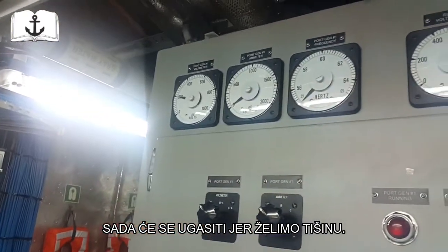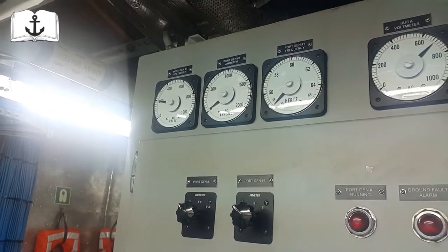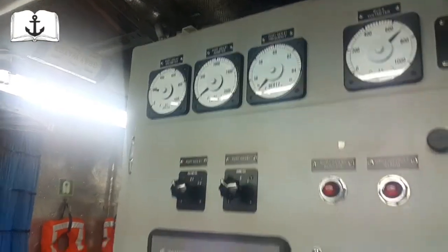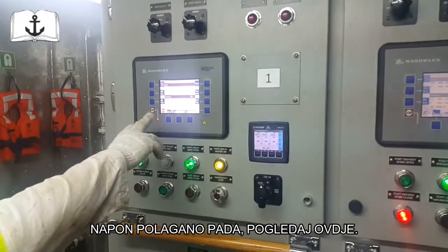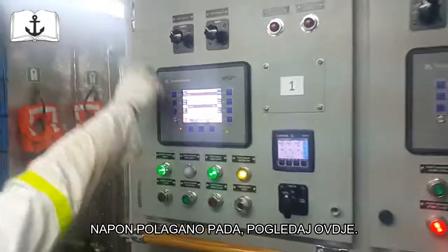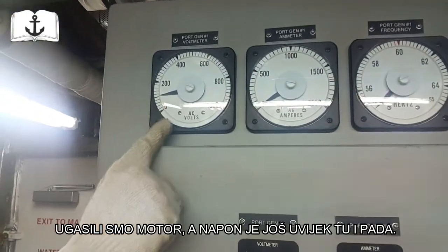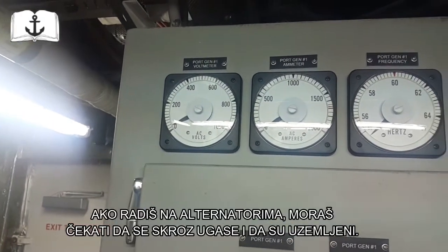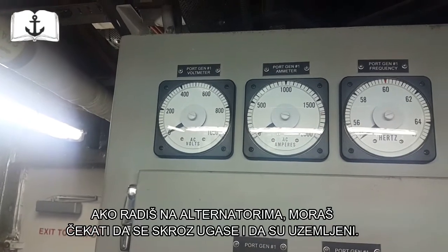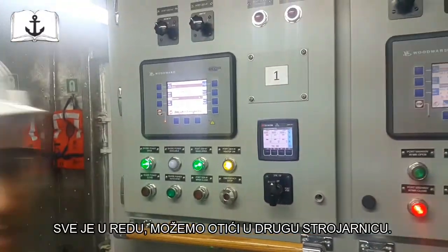Because we want quiet. Nice. Yeah, slowly you see, slowly the voltage is going down. It's not like you suddenly don't have voltage. Look here. The engine was stopped maybe 30 seconds ago, and still voltage going down. That's why you must be careful if you're working on the alternator. It should be stopped, but also should be earthed. Okay. Yeah, we are okay, so we can go to the other engine room.